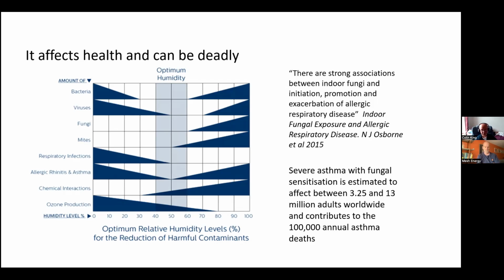And then it actually reduces the risk of doing this. And that's where the issues kick in, when people perhaps don't live as appropriately as they should. They turn off ventilation systems, they block up vents, they don't use or don't have undercuts on the door. And it's about understanding the importance of the ventilation system in this whole conundrum of reducing the health risks associated with damp and mould. So yes, people do have a part to play with it, but it's not really as big as perhaps we've in the past thought it as. So it's about delivering this conundrum and jigsaw of moisture balance.